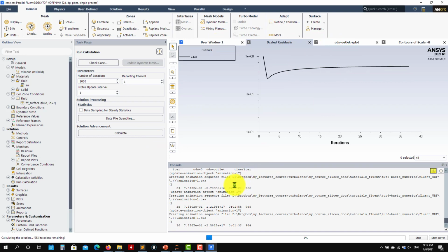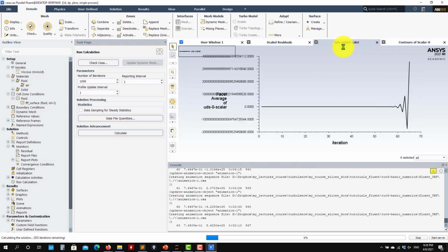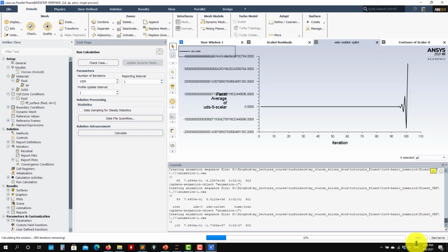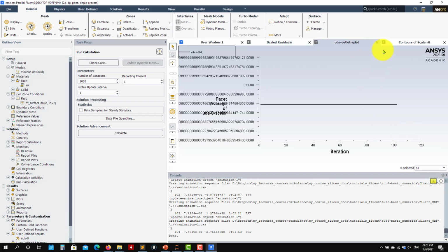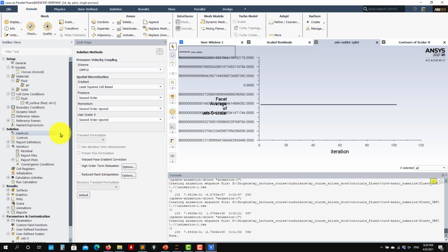See that this value is a super large value. See how a solver diverges. Even commercial software, if you know what you're doing, you can make it diverge. Again, this is not a standard practice. Please avoid this, but I just wanted to show you. And this is when I talk about an unbounded solution. This is a bounded solution that shouldn't be larger than 1. See that it's becoming unbounded, and it's just because you are not controlling this under relaxation. If you change this, nothing will happen, and you will still diverge.